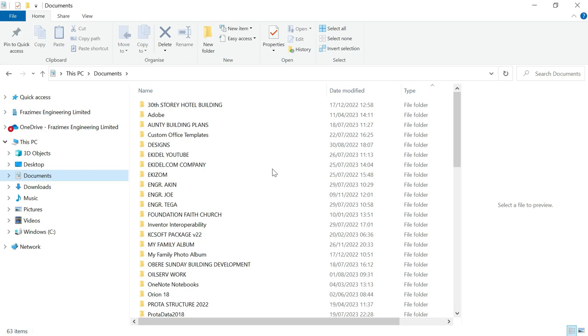How to know that it's a fancy block wall: if it had been a column, they would have changed the color or the line weight from the major block wall layer color or line weight. But if you look at that one, it has the same line weight and the same color as the block walls exactly. That tells you that that is a short block wall.